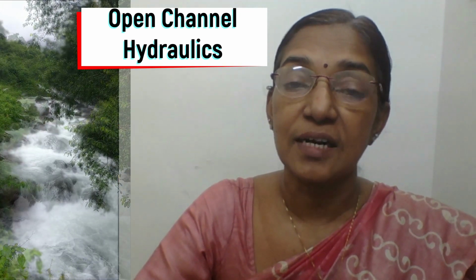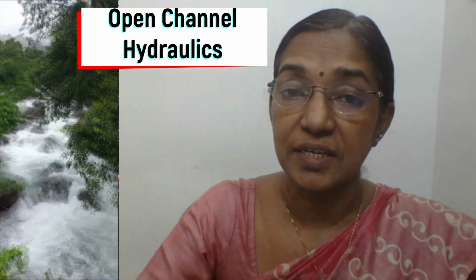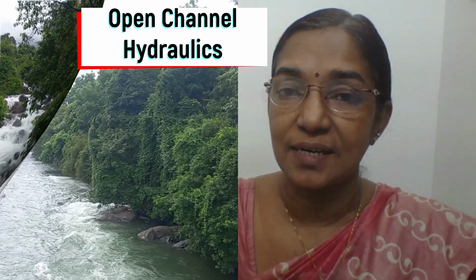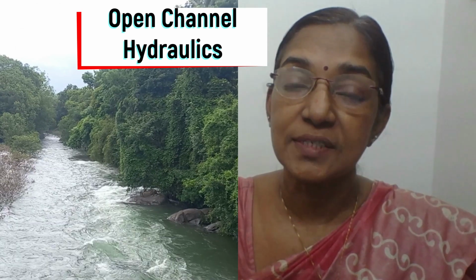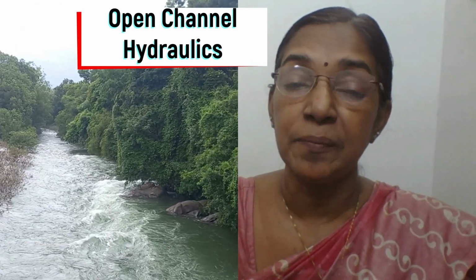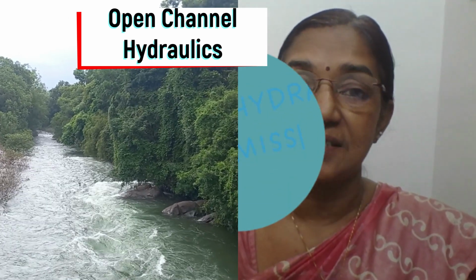Open channels are classified into natural channels and artificial channels. Rivers, streams, etc. are natural channels. So you can see that for natural channels, the cross-section of the channel and the slope are varying from section to section, and roughness of the channel also varies in a wide range.